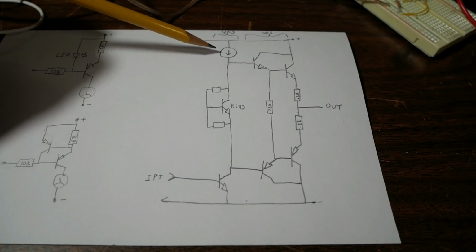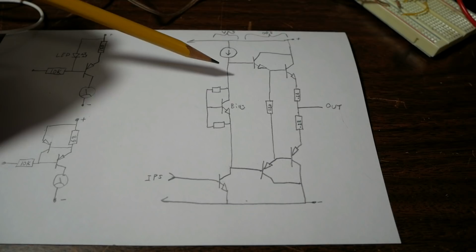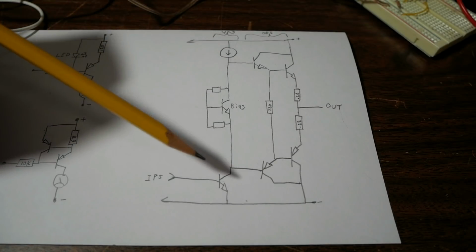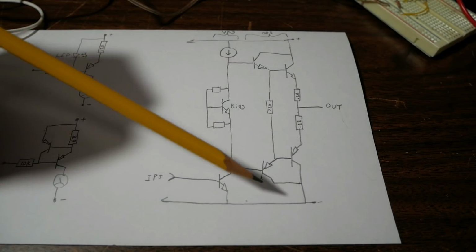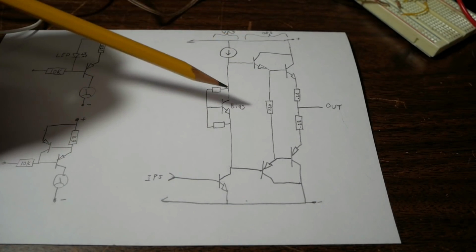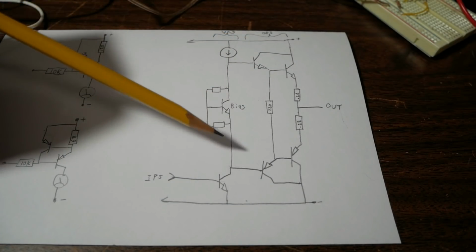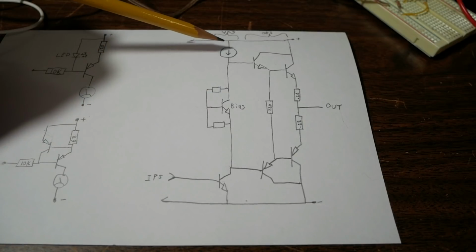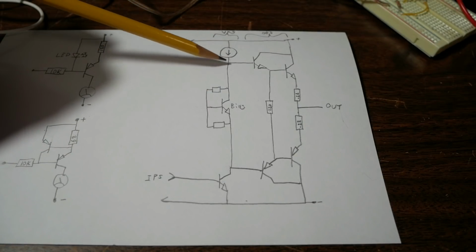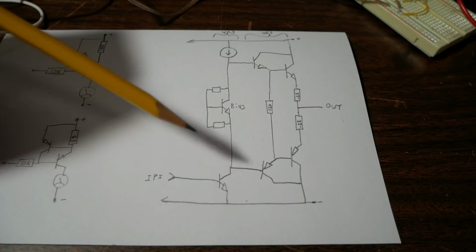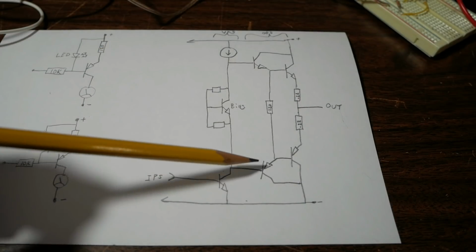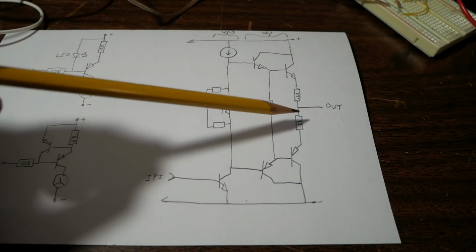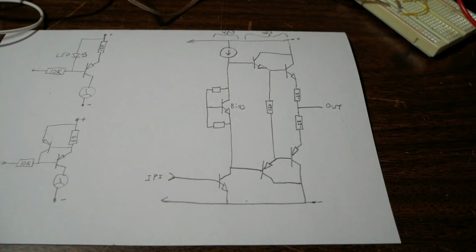But what are the properties of a constant current source? Well, one thing you can probably guess, it keeps a constant current. As I said previously, there's going to be a very large voltage swing in the VAS stage. So regardless of that voltage, we want this to deliver a constant current. That way the output stage always gets the correct amount of current it needs for driving the load.